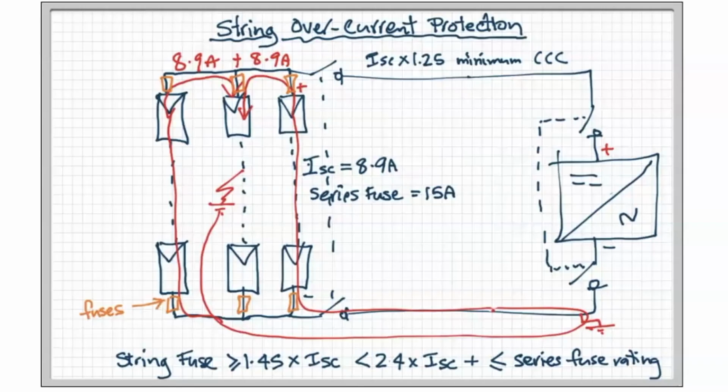Imagine that instead of those orange fuses that I drew, so I'll just bring that picture back up, you had blocking diodes. Then you would prevent that reverse current flow. But now you've got another problem, particularly in an LV system. You've got diodes which are going to get hot. They're probably going to need to be on a heatsink. That heatsink would need to be double insulated. You start to get a lot of cost going into this. It's still used in some countries in combiner boxes, particularly for large scale systems, but very uncommon in a commercial or residential system.